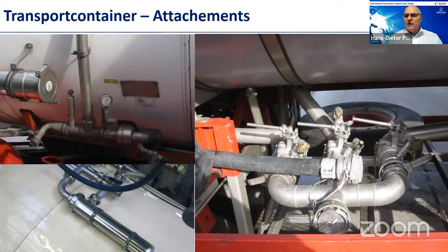How does it look? You have pipes for the unloading. You have valves. You have hand valves. You have hoses, flexible hoses for loading. You have something that looks like airlines. And all these parts can come directly in contact with the product, and after the transport they also have to be cleaned to make sure that they do not give cross-contamination back at the next loading.